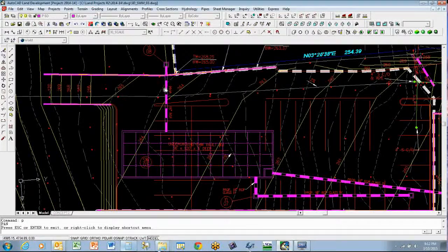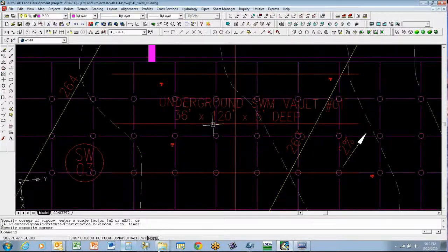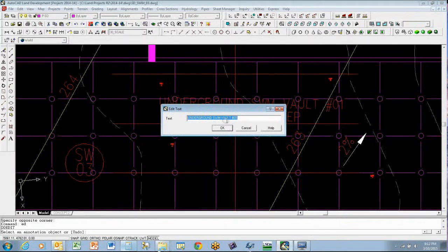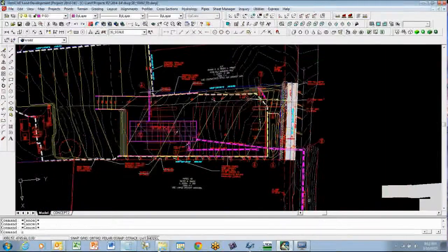This is a yard inlet, and we call it YI08, yard inlet 08. And that is dumping into a stormwater management vault. So we need to make sure that we get a profile of that section, of that pipe, from YI08 all the way to the stormwater management vault. And this stormwater management vault is actually number 02. So I'm going to edit this now and go ahead and correct that. And this is number 02, and so we'll call this SW02.